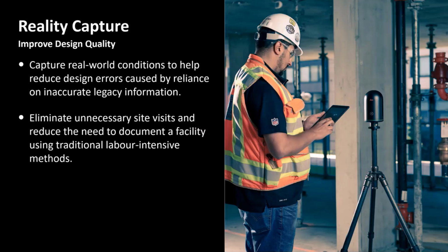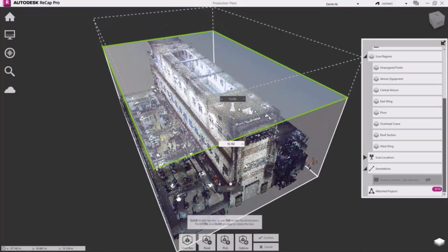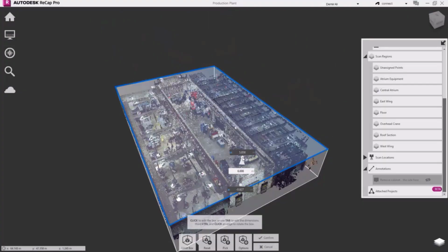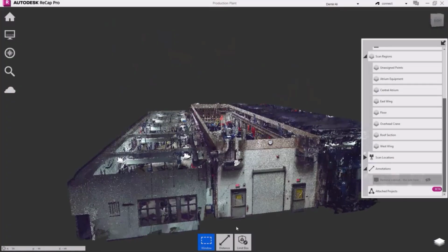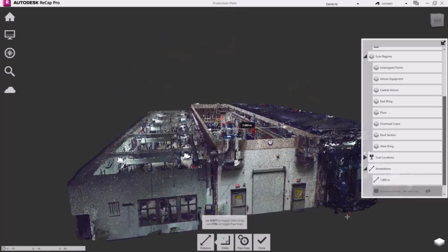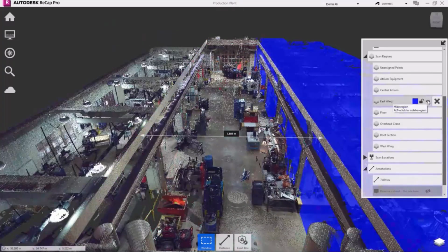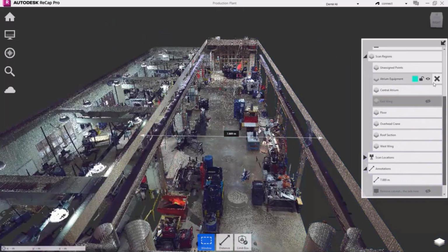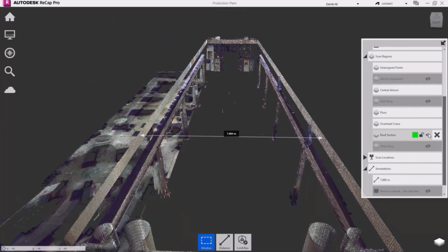Now, in a condition where we already have a planned factory, but we also have point cloud data, maybe they use their own 3D scanner or hire a consultant to do it, using common brands like Topcon, Leica and so on. After that, Autodesk has an application called ReCap Pro that will process all the point cloud data and clean up whatever is not needed.